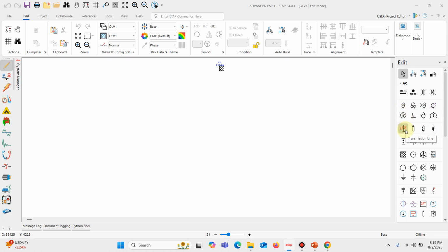So assuming I'm looking for a bus bar and I really do not know the location or the symbol of this bus bar, all I need to do is hover around until I see this is a node and I see a bus. Okay, this one is actually written bus. So if you click on it, you can see it follows me everywhere I go until I come over here on my workspace. I click on the workspace and I've dropped the bus bar.